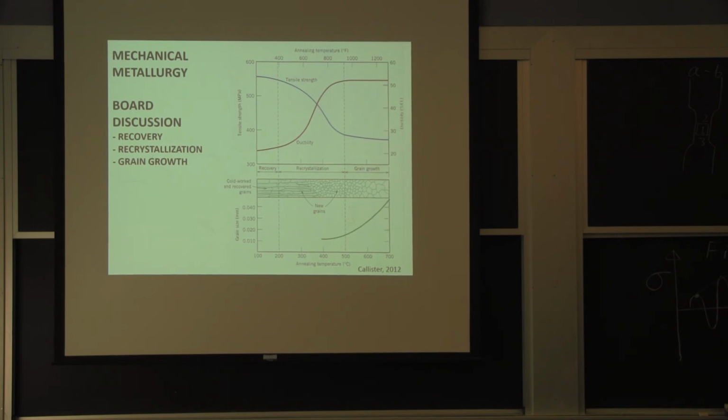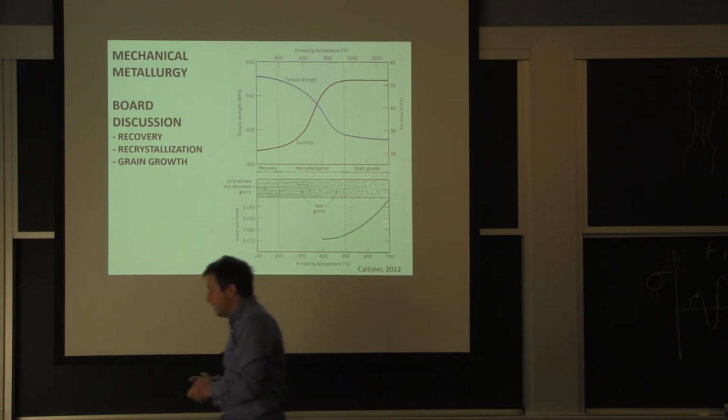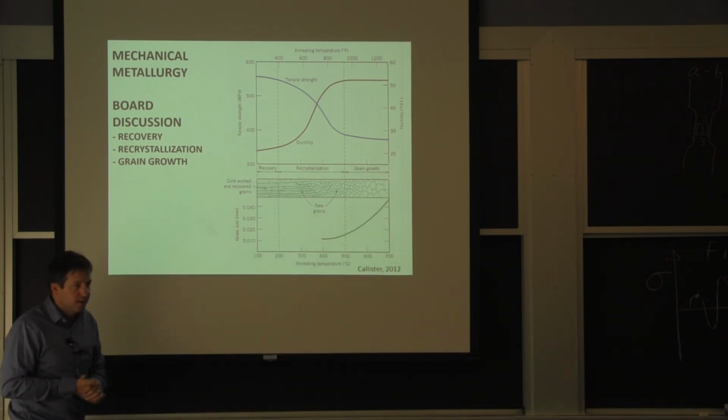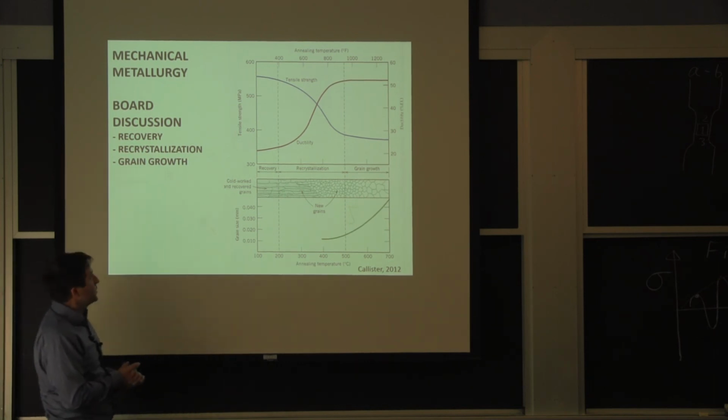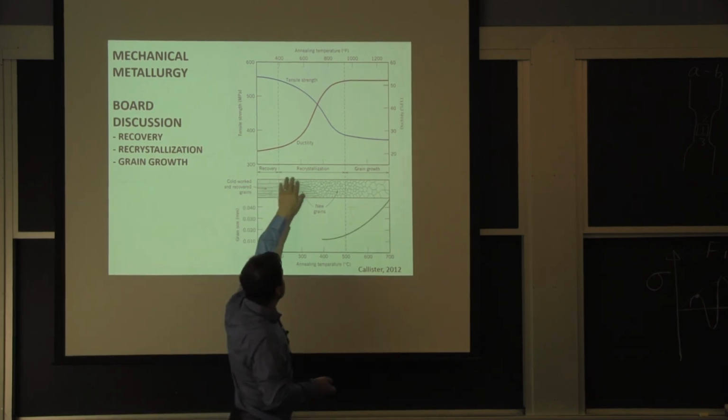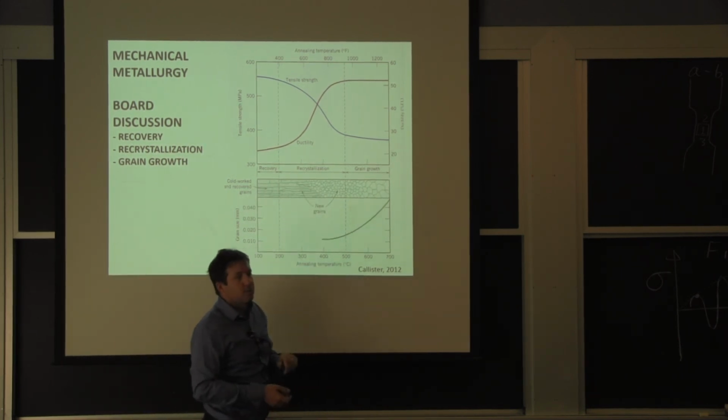That tends to be not all that big. Depending on the temperature you're at, it's hard for the dislocation to move. If you do it at relatively low temperature for a long period of time, that's where you can get that done. But a lot of times what we end up doing is we heat it enough that we get into this recrystallization mode.